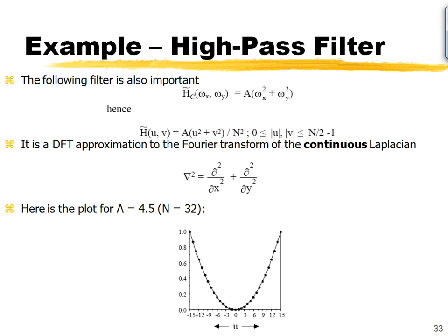The reason we end up getting low-pass filtering properties is that the dominant amount of energy retained, all the coefficients or intensities retained, are coming from the frequencies that are contributing in the low region, and the high regions are getting attenuated. So the high regions get closer and closer to zero.